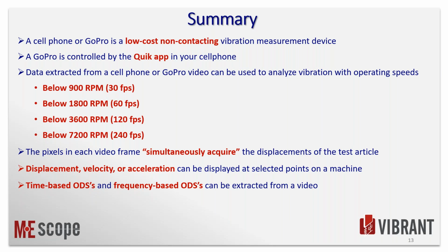So I get a spectrum from DC to 900, or 0 to 1800. Most of them we're going to look at here are 0 to 1800 RPM, but we actually have software we can unfold out to 3600 RPM, which is the sample rate of 60 FPS. 60 times 60 is 3600 RPM sample rate.